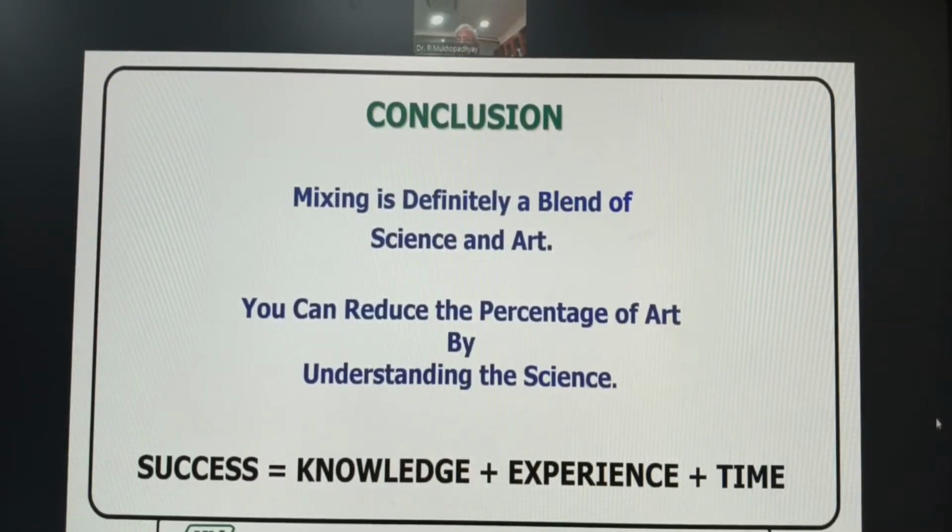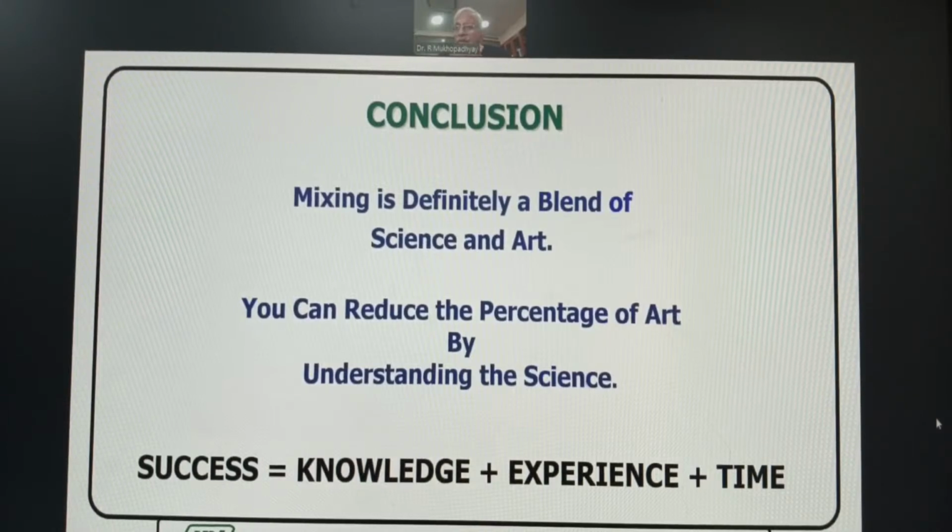Let me be very clear. I will give you a simple example of why knowledge is very important. Suppose some blooming comes on the surface, or some porosity comes, etc. We go for a fix certainly without analyzing that. Let me be very clear. If a porosity comes, you take the sample. If a bubble or blister comes, you cut it.